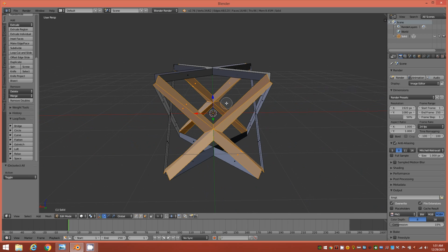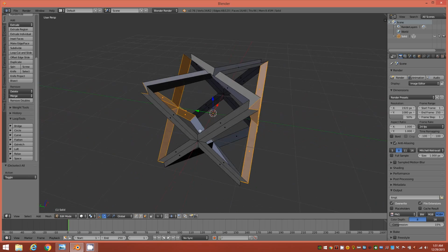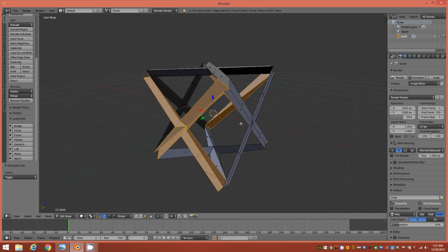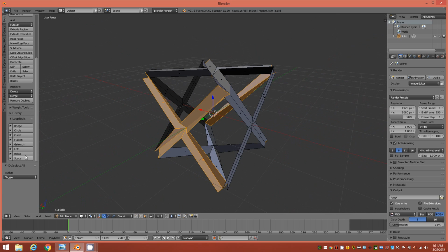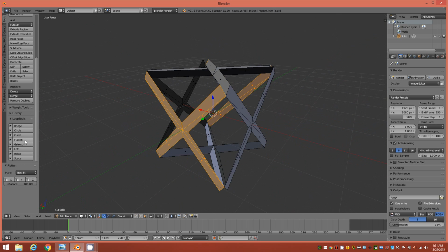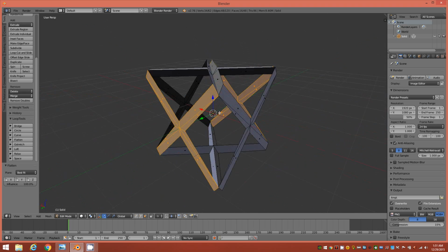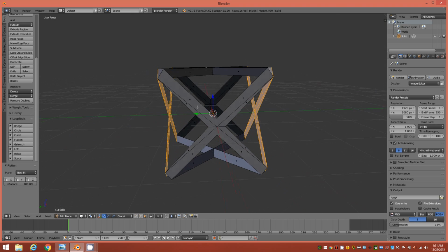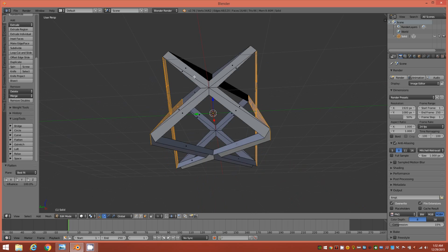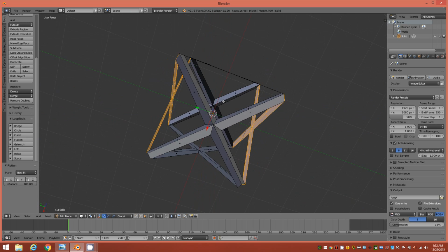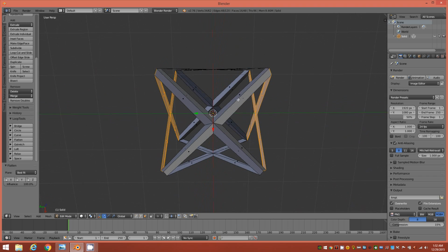Now we can right click to drop the tool and look around real quick to make sure we have only the faces we want selected, and then go over to your Loop Tools once again and click on Flatten. Now we've got those flattened out. Now we'll go to this next group of faces here, and we'll do the same thing.